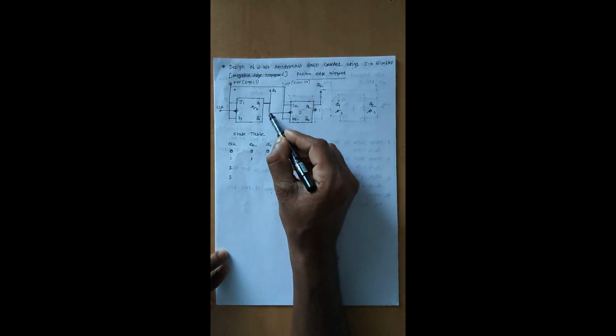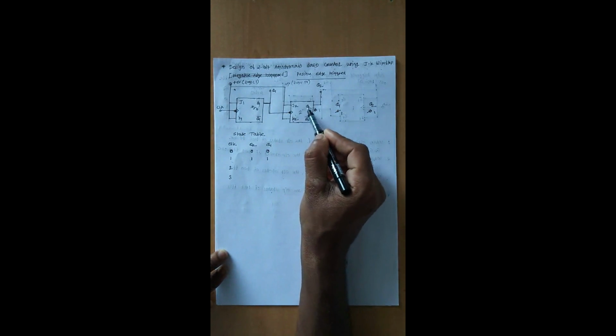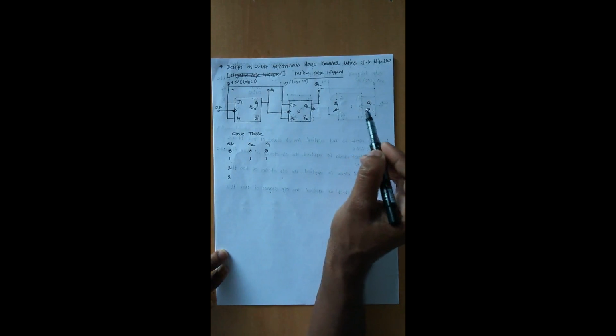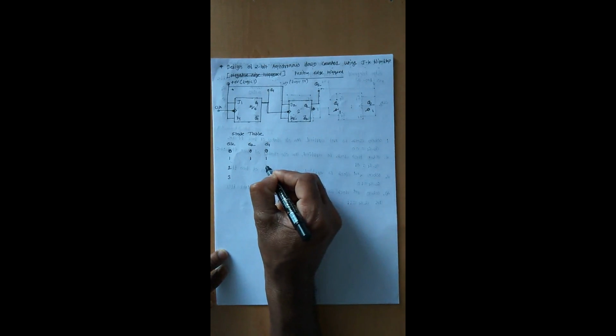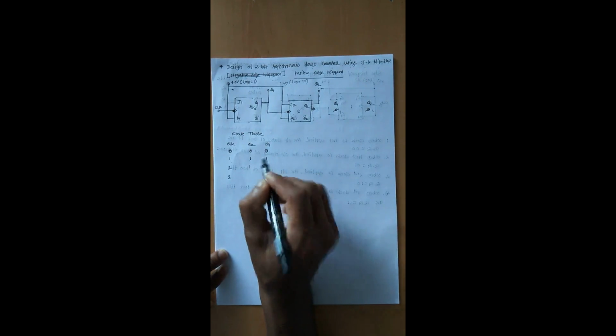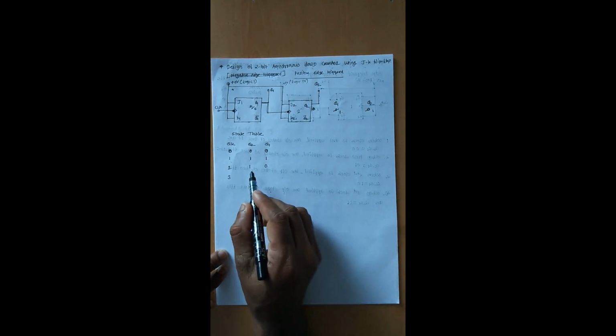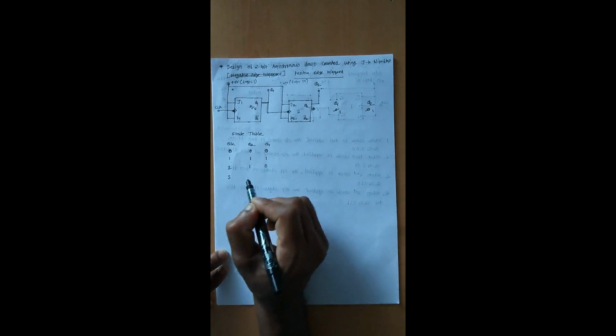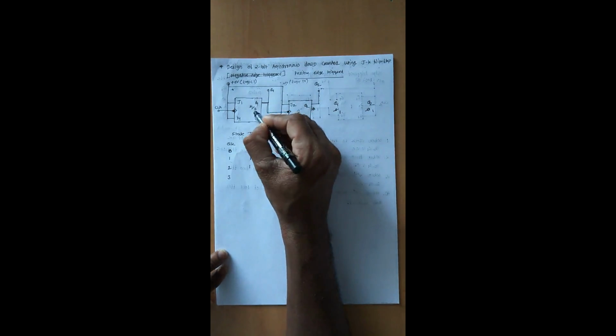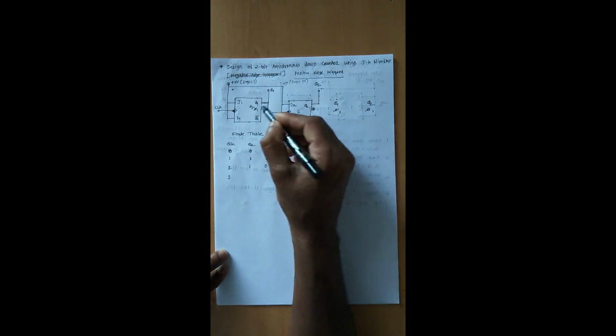Due to this, no clock is applied to the second flip-flop and the second flip-flop is in the off condition. So this bit will be 0 and will not be changed, so it stays as it is, 1. Okay, when the third clock is applied, again this 0 is going to be changed to 1 because of the toggling condition, which 1 is present here.